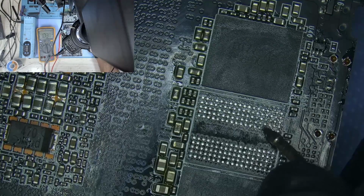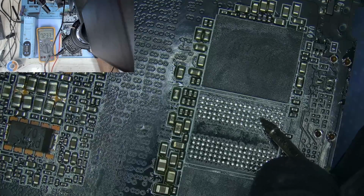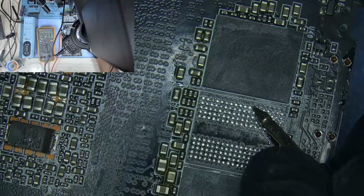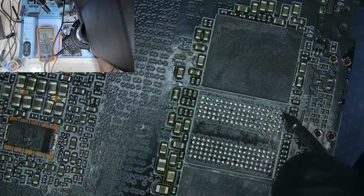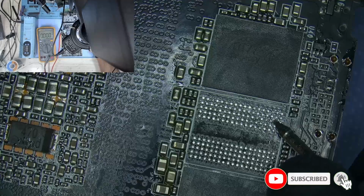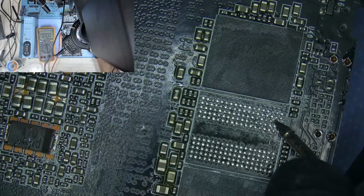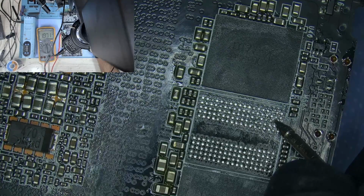The rest of the pads are fine. I don't see any shorts there. All the other data pads are good. They show me a good reading, except for one which is shorted to ground. So it could be that this was the reason why we have that error. That's why I measure the data pads, just to make sure that there's no short on the data lines. And we found our fault.